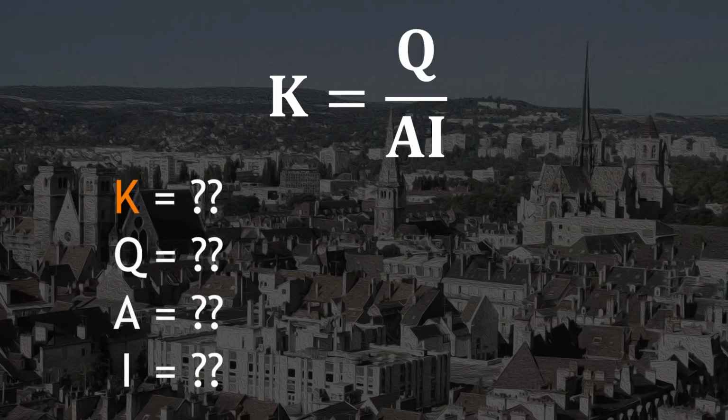Equipment ready and water flowing at a steady state, we can now use the Darcy tube to determine the hydraulic conductivity, the K variable in Darcy's law, by observing the discharge rate and hydraulic gradient. This will provide us with a quantifiable value of the material's ability to transmit water.